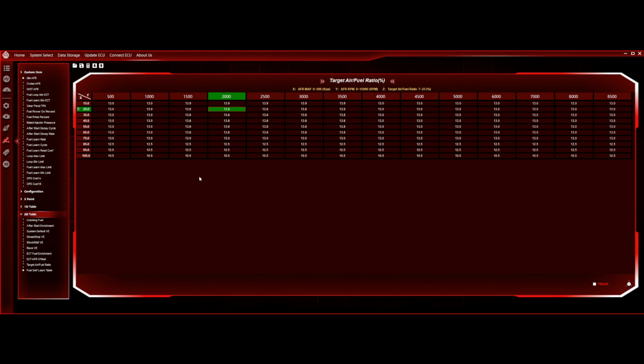While your system's running, we'll go on here and say that at this area it's reading like a 13.9. So it's actually slightly leaner than what this number is. What we'll do is go in here and increase your number.